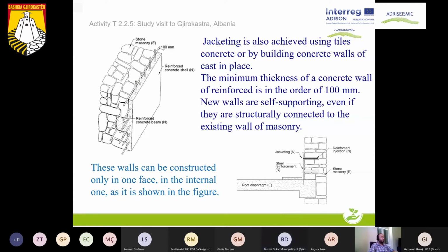And as it is clearly also explained by the picture, we mainly used for the mosque of Gjirokastra Bazaar the grilling, the iron grilling, for a better supporting methodology and also to have a better outcome for the supporting wall only. And you can see that we did not use the previous jacketing method in the same way as we are doing in this particular supporting wall.